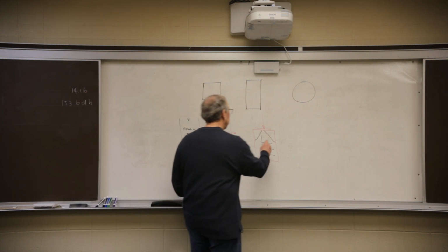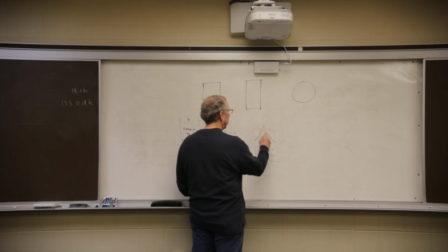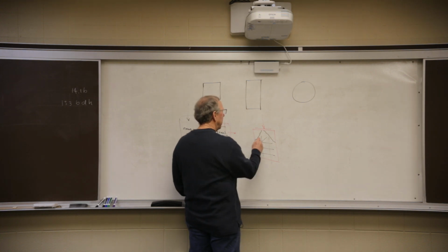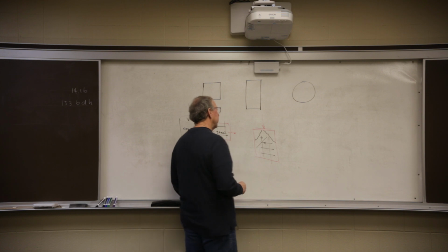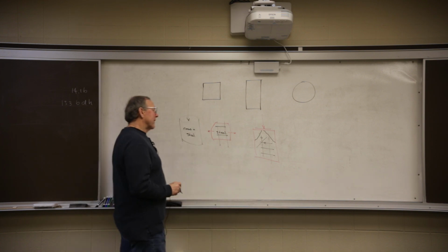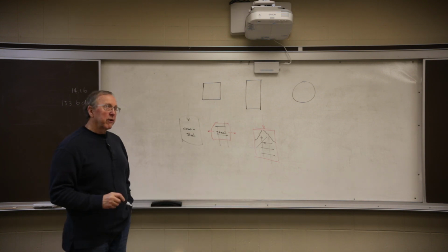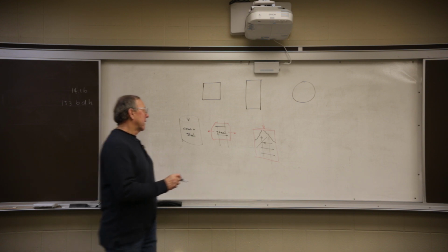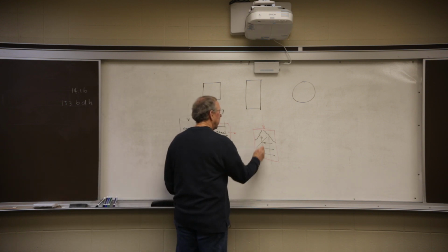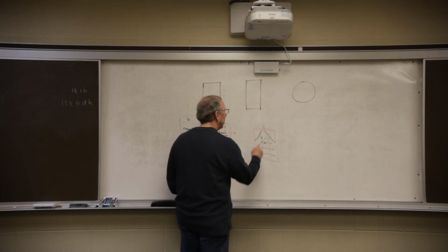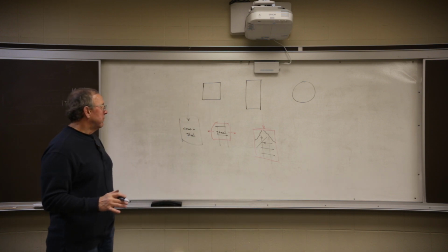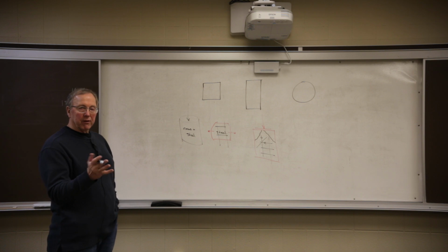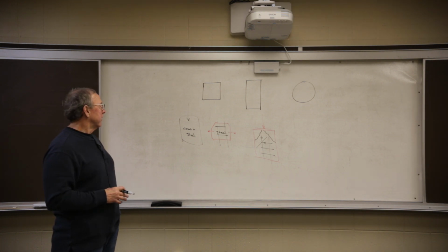So here, since we've got a vertical and a horizontal and our force is on an angle, part of the force is taken out by the vertical, part by the horizontal. And it does have some shear value, the concrete. So the concrete takes care of part of this force, and the steel aids it and adds a horizontal and vertical component to take out the 45-degree angle shear force.